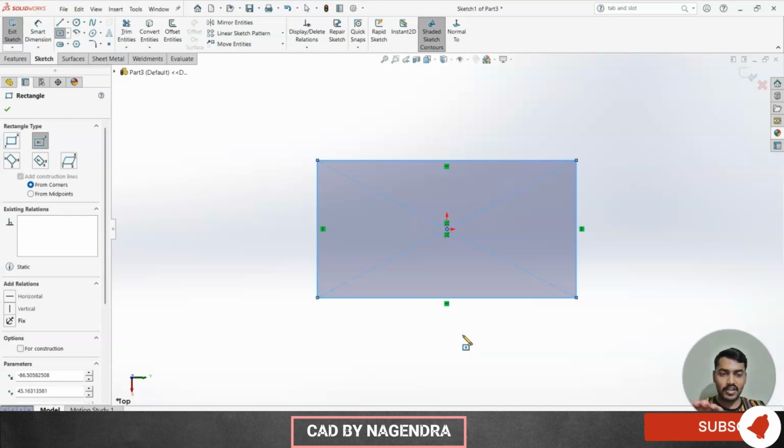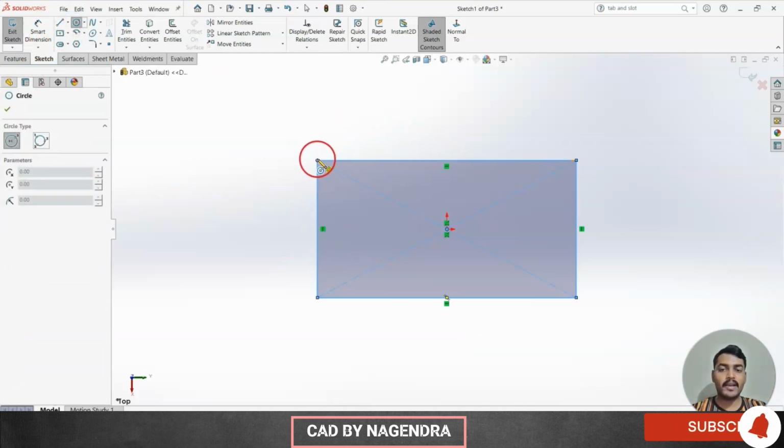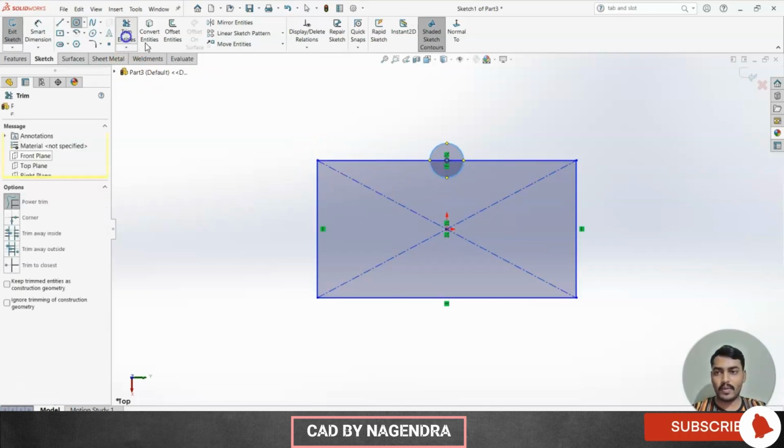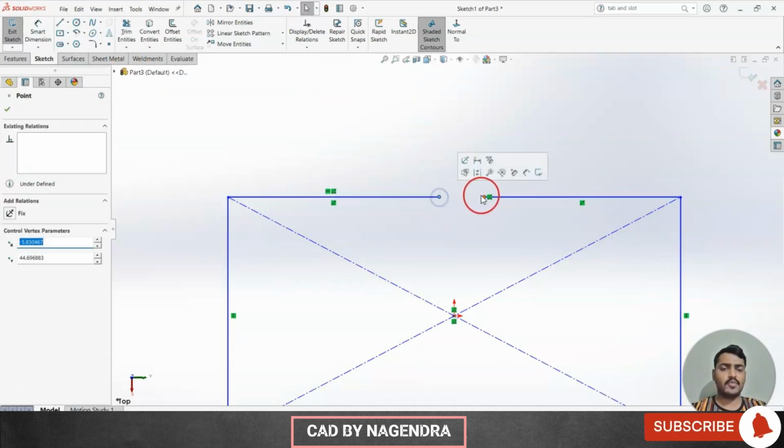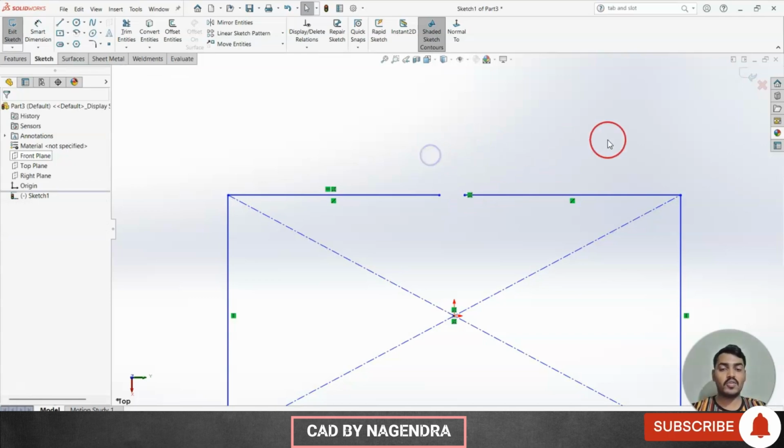We'll take one flat sheet. That flat sheet, in which shape we want, we will bend it. Somewhere we will do a welding operation or clinching operation, one extra operation we are going to perform to join or to merge these two sheets. So this joining part is there, right? There should be an opening line. So to provide that opening line, this profile should not be a closed profile, it should be an open profile. So just to make it an open profile, I'll create like this. This gap should be little, but it should not be a closed profile.